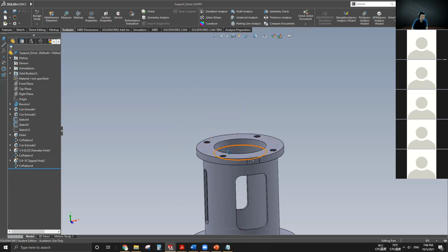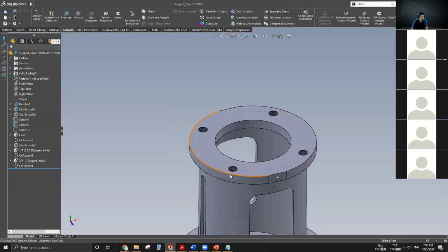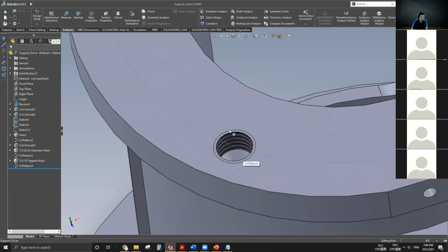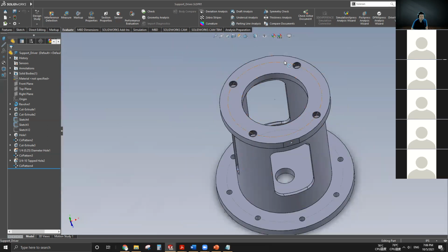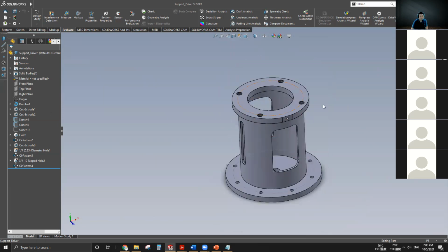The motor base is circular, with the same or smaller diameter than the OD of the top plate. These 4 holes with cosmetic thread are going to secure the motor. The motor will have another 4 holes, and when the motor is sitting on top, these 4 holes match position, and you're going to have bolts and nuts to secure the motor on top.